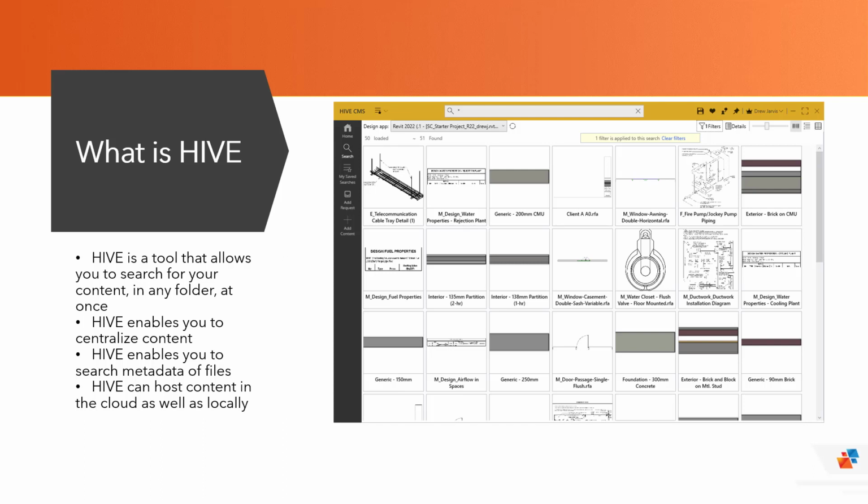Now, this enables me to set up company standard work sets and make sure that my links and other starting elements are on the correct work set. I can even then use those work sets for filtering my views. So these are benefits that you don't get if you use a template file, but you can if you start with a Revit project file. So in order to do that, you just have to remember, start the project by detaching, save it into a new location to become your central model.